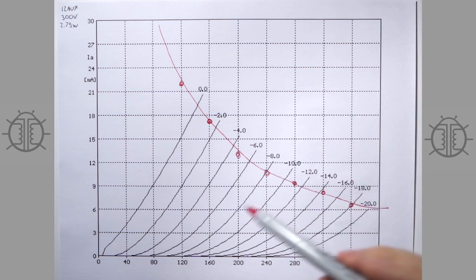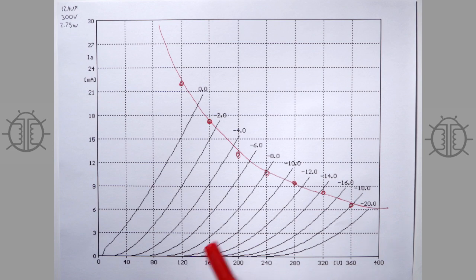And so we're now going to look at the various DC operating points that we can pick. Now, usually a driver stage like this is going to be loaded by a resistance. You can do choke loaded, but generally speaking, you load it with a resistance, and so that means the voltage can only swing up to the supply voltage that you have, and so we'll have to keep that in mind when picking a DC operating point.